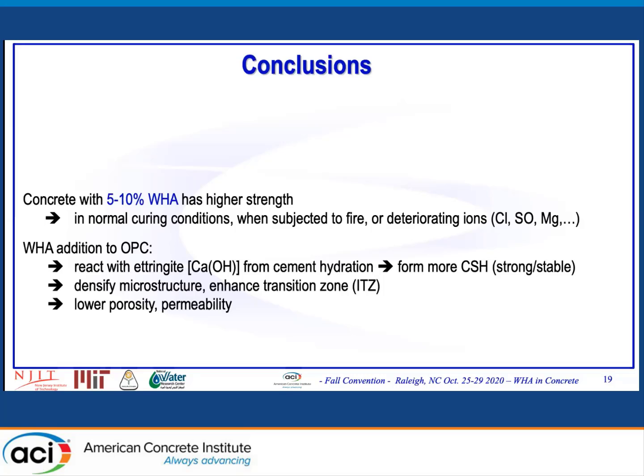it reacts with the ettringite and transforms it to a strong formation of CSH, and it densifies the microstructure, and also enhances the interfacial transition zone (ITZ), thus lowering the porosity and permeability. So it's protecting your concrete against any deteriorating effects.